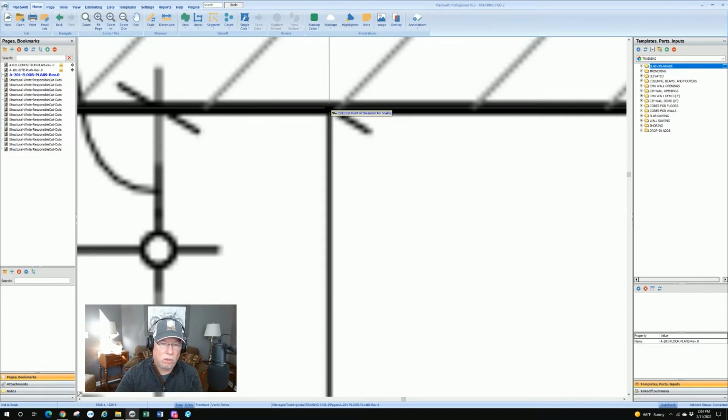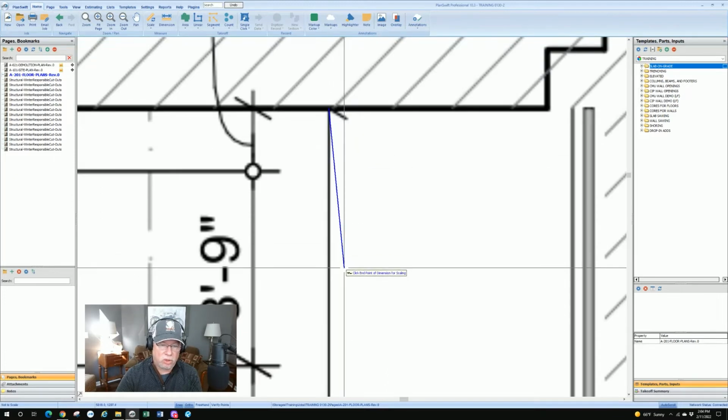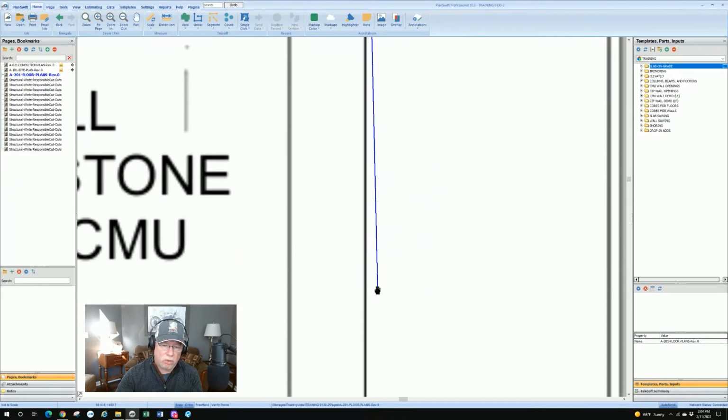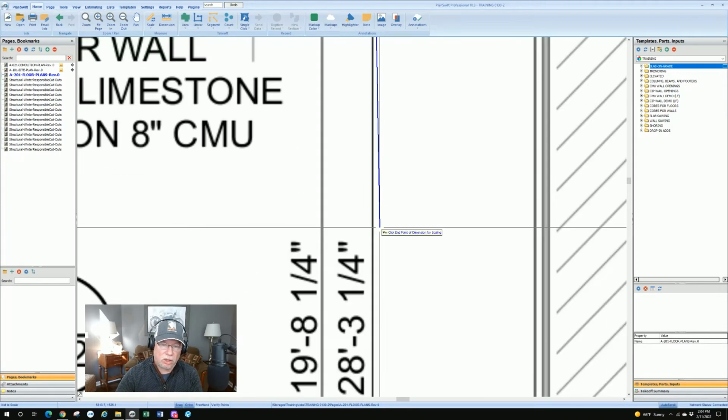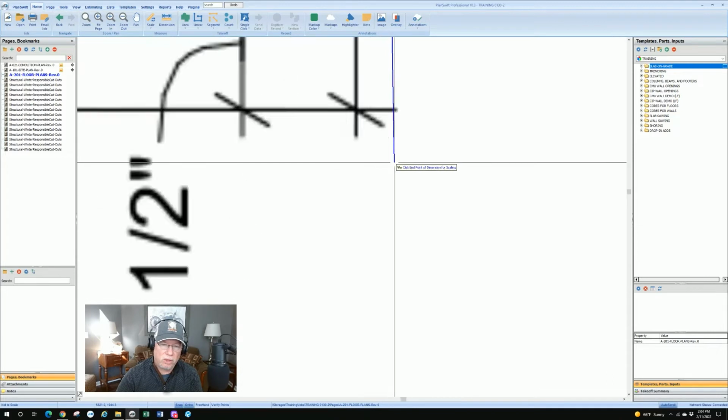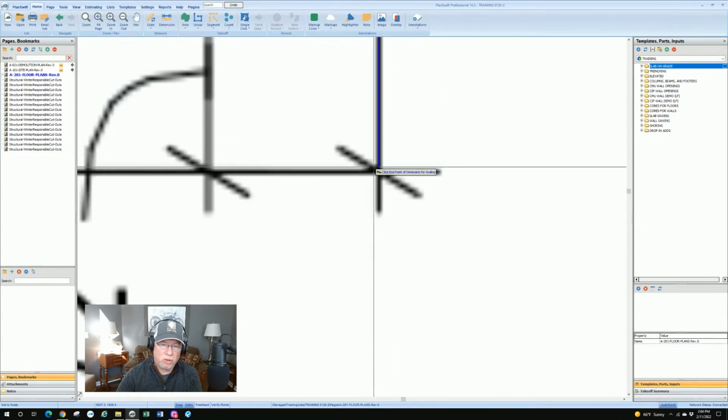So we're going to click there, and you can use your right mouse button to move around, and you see that pan figure come up without losing your scrolling. And I can also zoom out, use the combination of the mouse to move around and zoom in as much as I can and get dead center. At the bottom there, your ortho should be set on, clicked on.